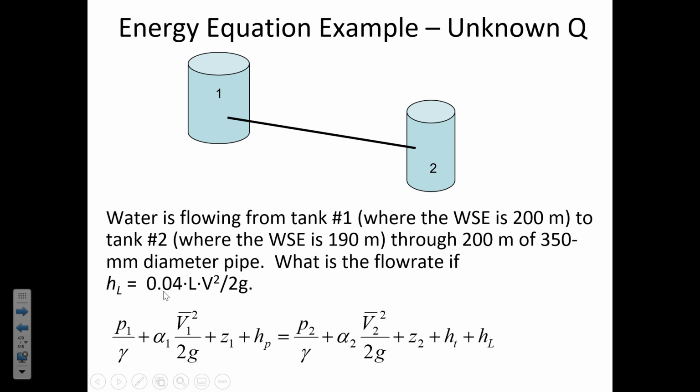So in this example, what we're saying is we've looked at how rough the pipe is. We've looked at whatever fittings and bends and valves there may be. And we're expressing the effect of all of those with this factor 0.04. Because the H sub F formula that we'll use a lot, the Darcy-Weisbach equation, is f L V squared divided by D 2g.